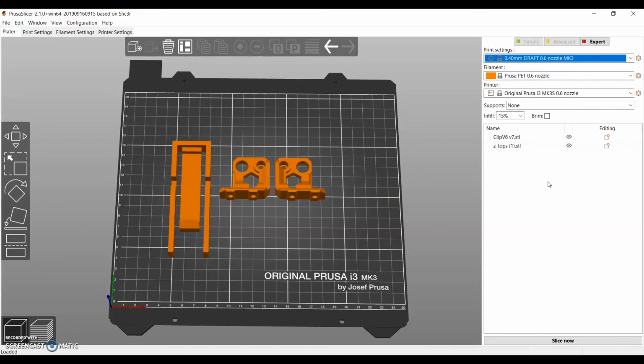And then next, we'll go over the infill percent. So 0 to 20% is usually used for non-functional parts, for pieces that do not need to withstand force. 20 to 40% is for light use parts, for functional parts which will undergo some force. And then 40 to 100% is for heavy use parts. But most commonly, 20 to 25% would work for many prints.